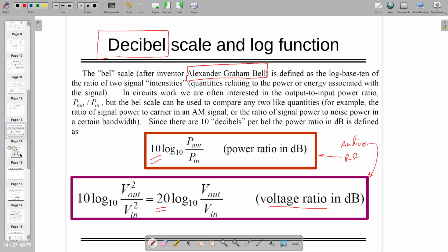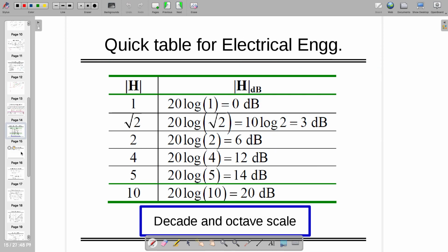And remember, this is the thing I am doing even in other higher courses, when we are going to talk about everything in dB. Like I'm telling that the gain of my amplifier is 60 dB. If the gain of my amplifier is 60 dB, I'm measuring in voltage. So what do you think in volt per volt? Very quick. 10 power 6 won't work. It's not 120 dB. 1000, yeah, somebody told 1000, right? So it's 10 raised to 3 because 20 log, right?